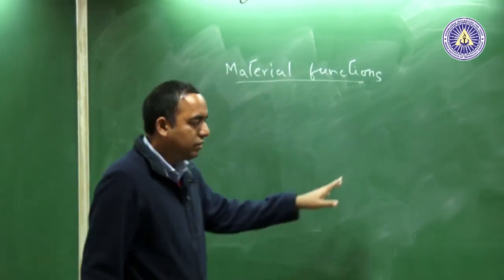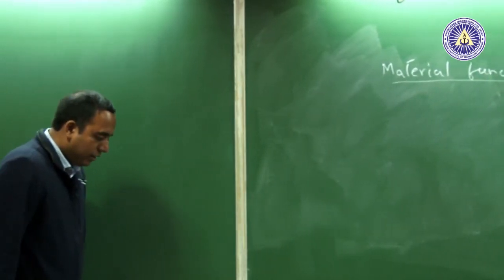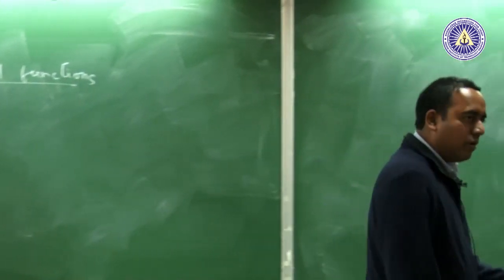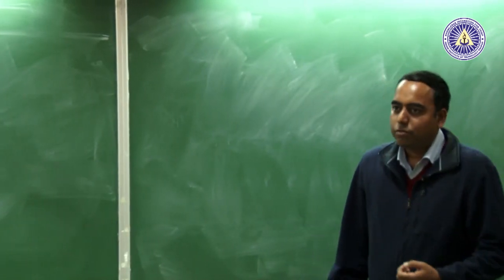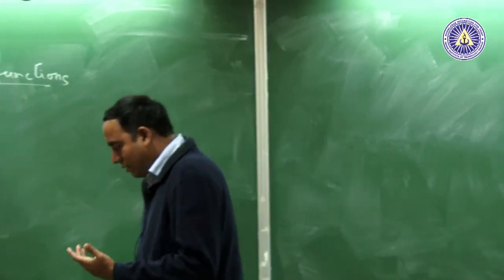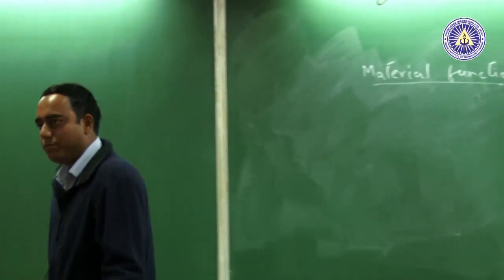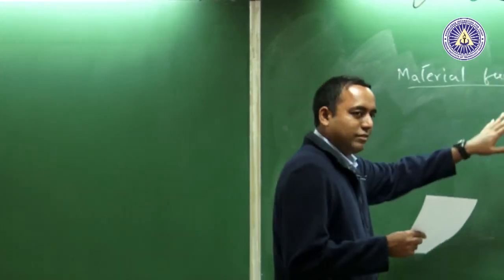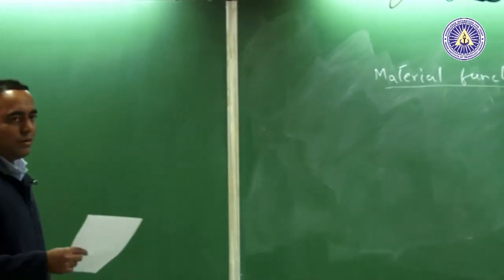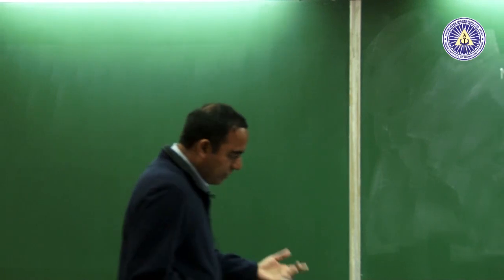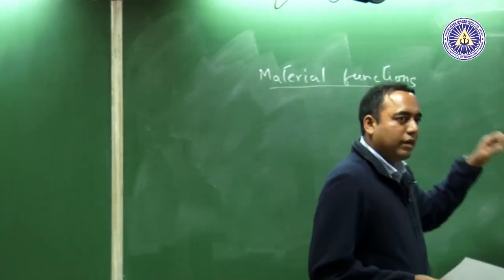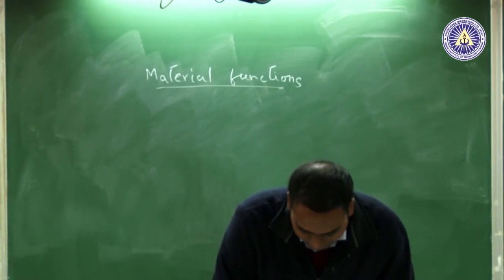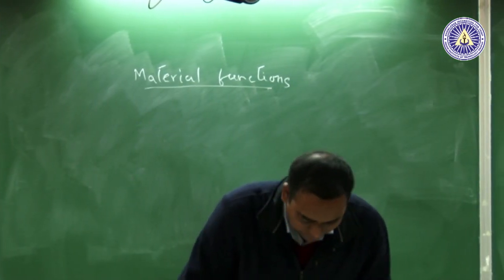There the viscosity is a constant. So, what was a material property, viscosity was a property of the material, now, since it is not a constant, that material property will be, and you will see that it is a function of the shear rate or the extensional rate that you impose. So, in some sense that material property has changed to a material function, which is why we have this whole term of material functions, and material functions are defined with respect to the standard flow that it is adhering to, which means that we have a shear and we have variants of shear.